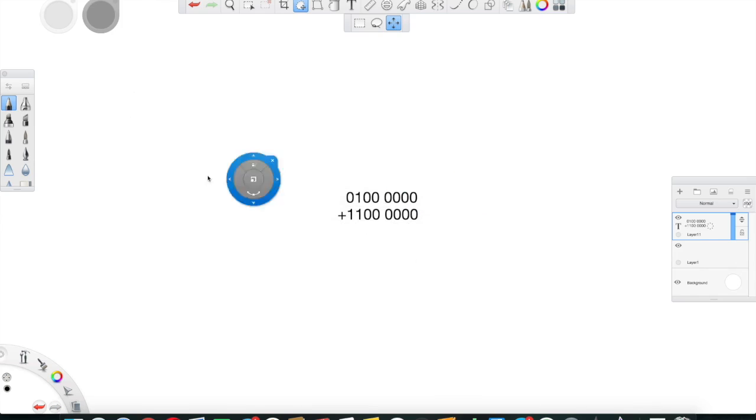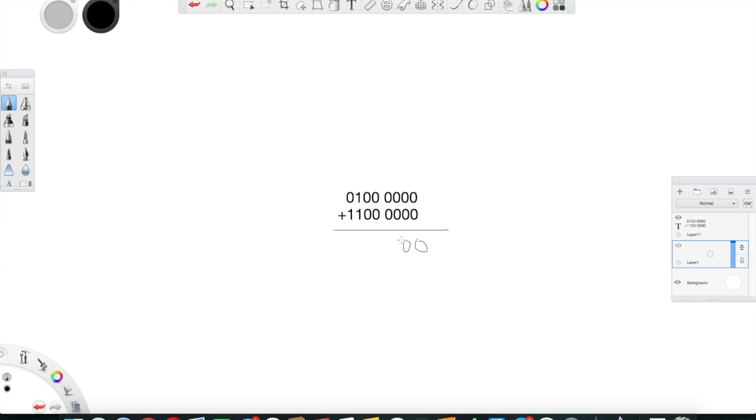And we click OK. We click on this and here. Well, here will result in 4 zeros. And here we'll have 0, 0, 1 plus 1, 0, carry 1. 1 plus 1 is what? 0, carry 1. So here my result is what? It's 8 zeros. It's a 0. So the Z flag will be equal to 1. Otherwise, if one of these 8 bits were at least 1, the Z flag will be 0.